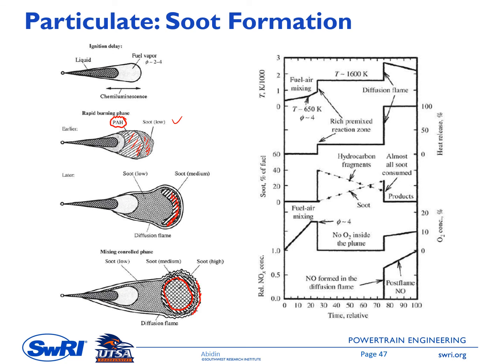And then the figure on the right side is showing the sequence of chemical reactions that occurs during the fuel spray development, combustion, and then fuel reaction, and the soot formation and oxidation. So in the middle here we have the soot formation. The soot is formed here during the combustion process, and then the majority of this soot will be oxidized, and then the net between the soot formation and the soot oxidation will be the soot production, and this soot production will exit the engine as the soot emission.